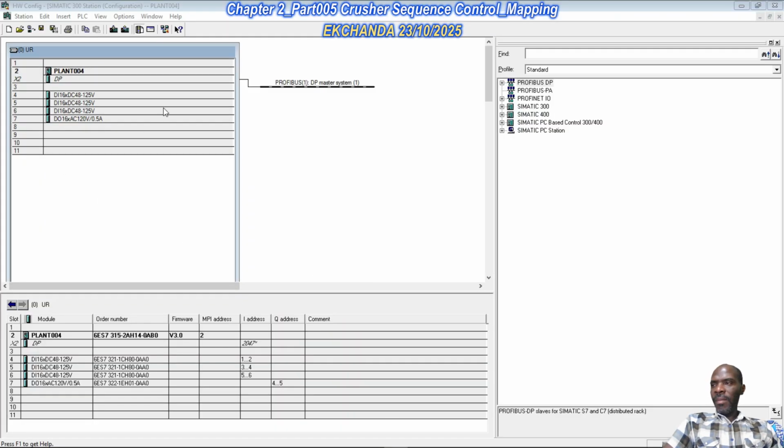So, input modules. In the hardware configuration we had digital input modules and digital output modules. Here we have the inputs, because we identified that besides ordinary input signals, there are input signals associated with protection functions, such as the emergency push buttons, the thermal overload, the earth leakage protection, and the emergency push buttons.